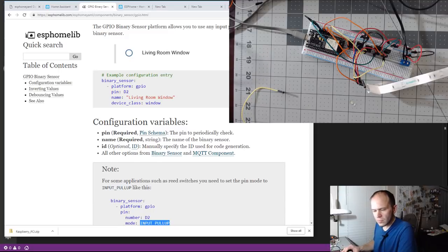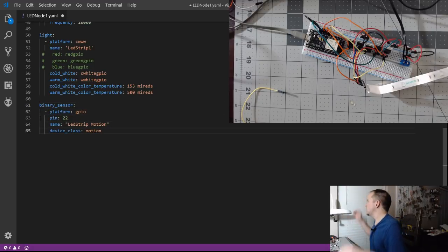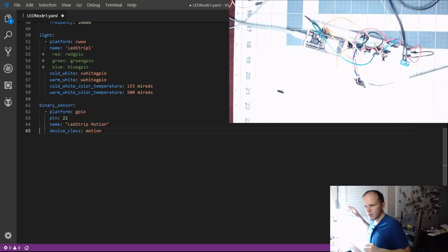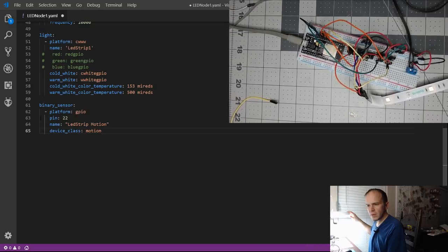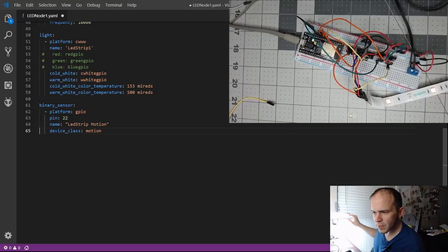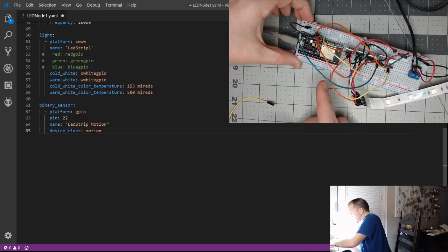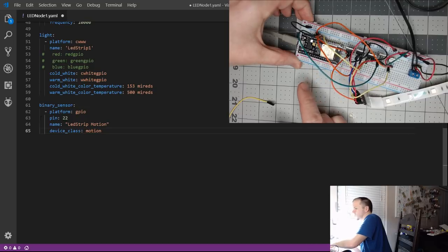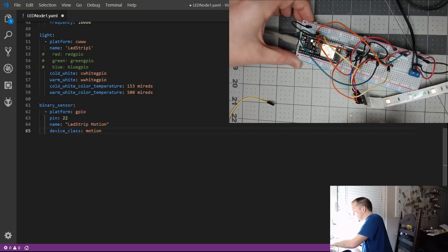So let's see. Let's find a decent GPIO pin to use this on. Let's see if we can put this a little closer for you guys without bumping the table and the camera too much. Sometimes there are certain GPIO pins you can't use on the ESP32, and there are several charts out there that say this one's input only or output only.